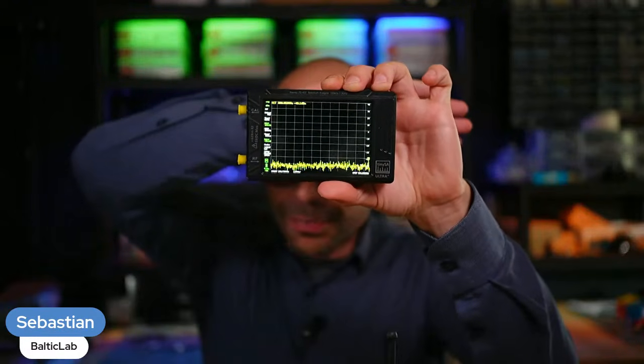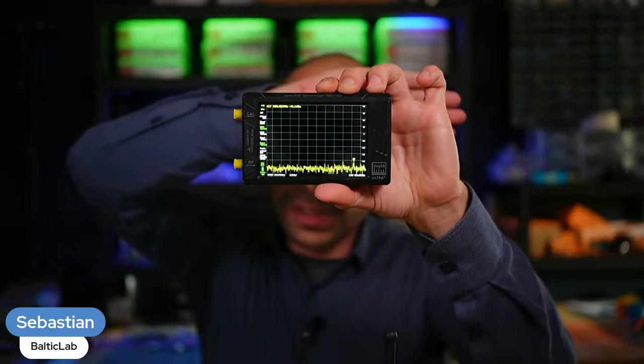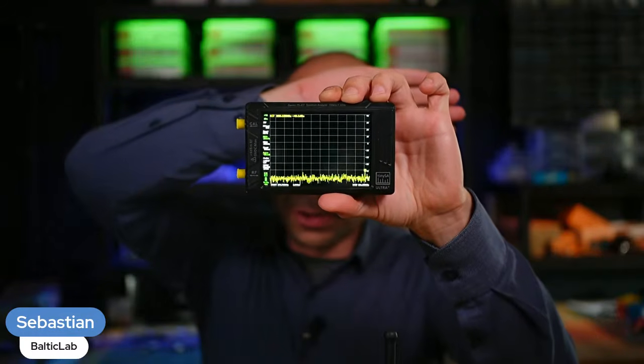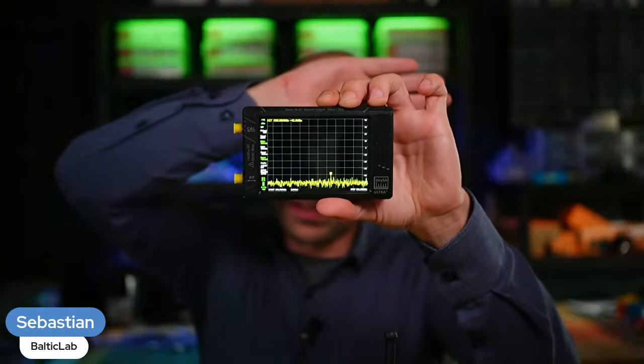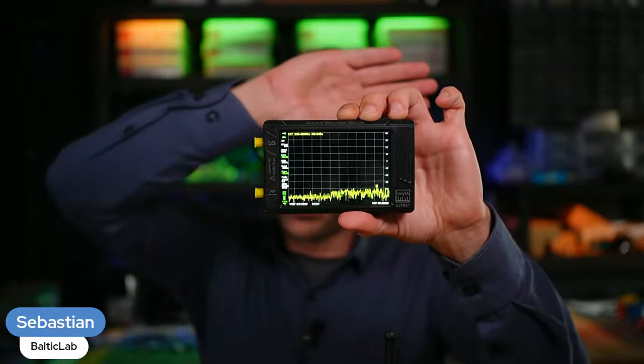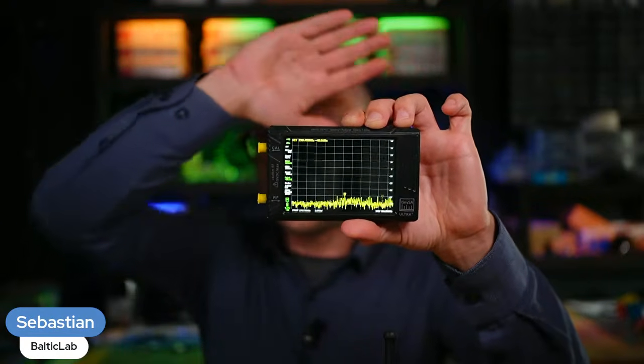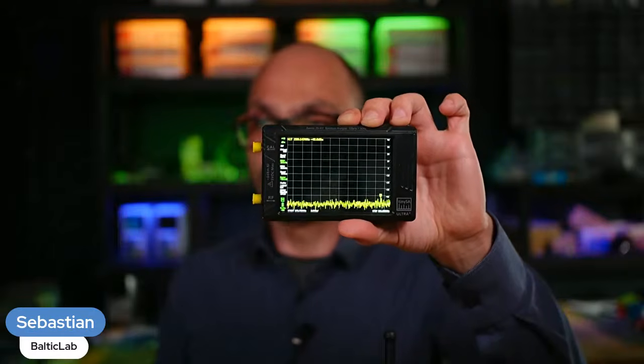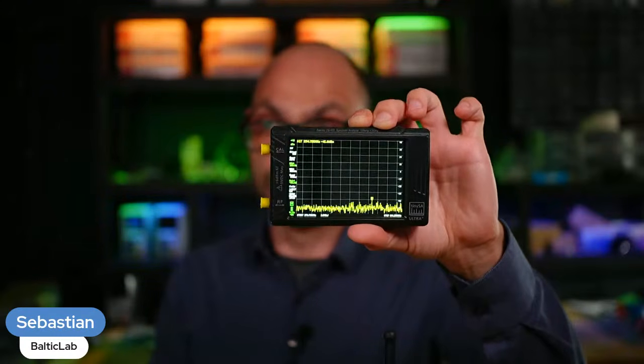Yeah. That's the TinySA Ultra that's going to be given away at the end of the show. And that one, for instance, has, I think, 450 points. So you can do the same measurements with that, but you will have to use a completely different span, around 22.5 megahertz, to get results. And we will get to that in a bit too.